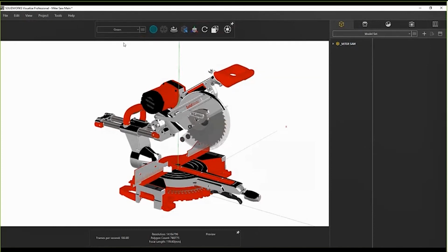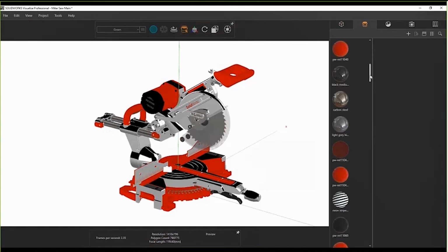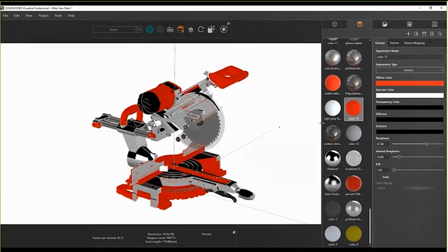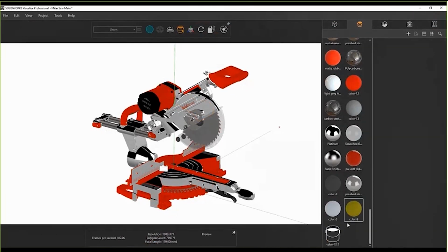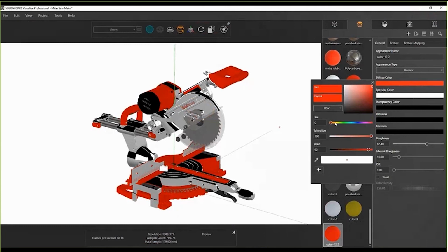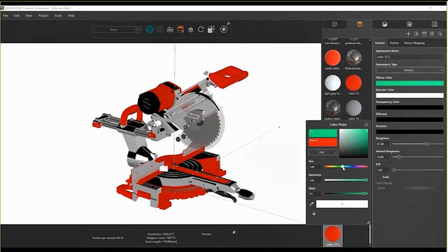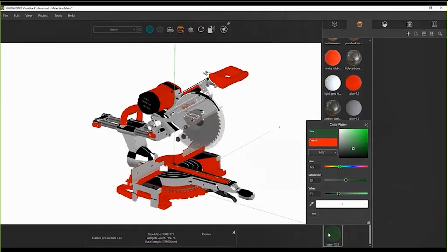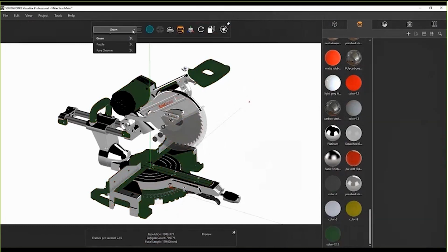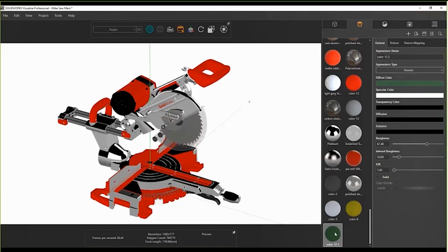additional configurations, okay? Now inside of here, I've got this color already applied in these handful of places. So what I'm going to want to do though is go ahead and copy and paste that color so that it's an individual appearance in that list. Now I'm going to go ahead and change it to whatever color I want. So we're going with that green. I can then drag it, drop it onto there, and now that configuration is my green configuration. And I can keep doing this, right, we've got our purple version.